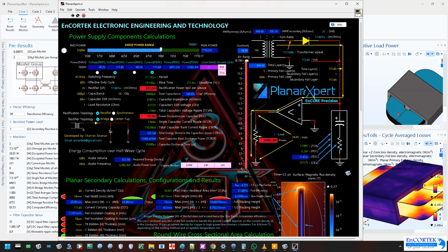And this is voltage going to the amplifier, and the amplifier with the load over here. So we're seeing 12,000 watts, right? Go RMS, right? We see 6,400 and something watts, right? So this is RMS and peak, right? So when you're looking at these guys, you'll see the power rating here. And so as I say, wherever you're going to design, you know the energy that you're working with for peak.